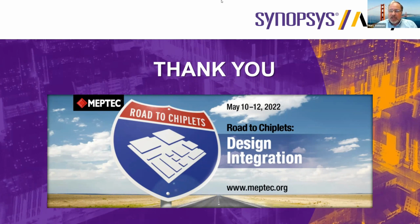But you can capture that in a chip power model and stack multiple chips on top of each other and converge on how they influence each other, how the temperature creates the power output, which creates the temperature, and finally get a consistent solution. So reduced order models can allow you to add them together and capture the interactions between them. But some aspects are not capturable or can't be broken apart into pieces.